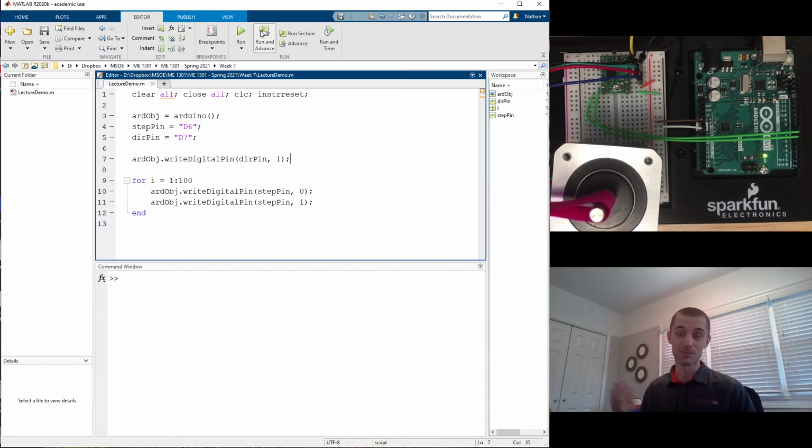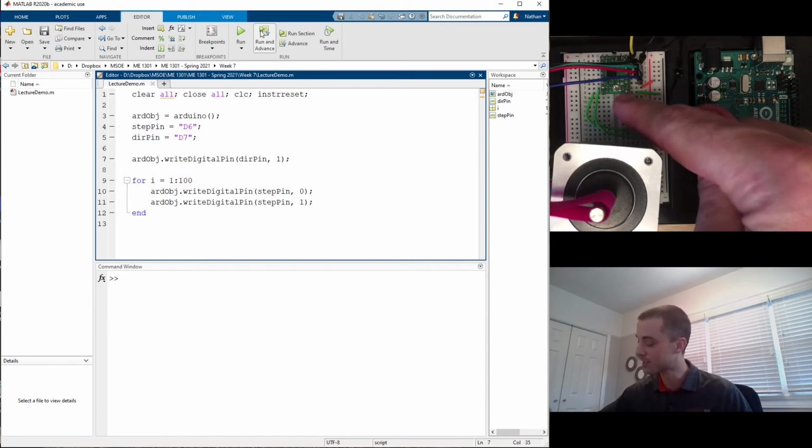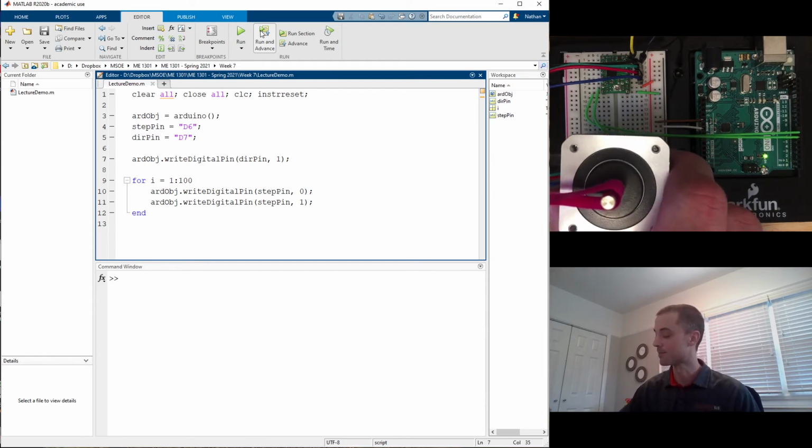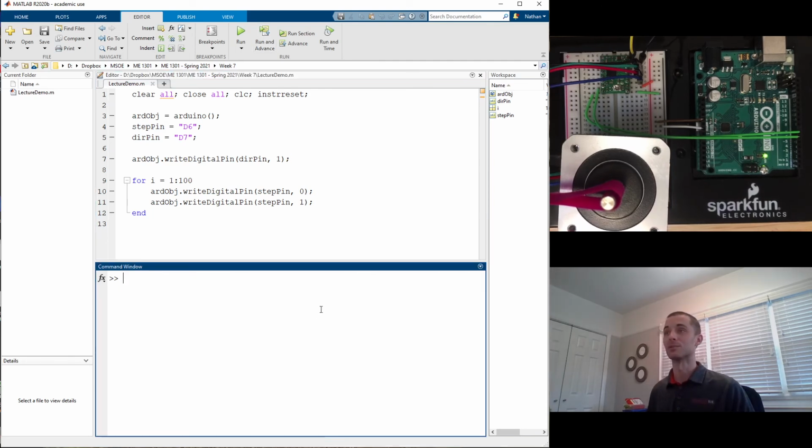If you do get some, which are incredibly cheap pretty much anywhere you order them from, one, make sure that your power supply is secured. But two, make sure you turn that little potentiometer so that you don't have too much current going through, because these chips, if you turn them up high enough, you can actually burn them out. It's not impossible to do, and I have a pile of partially burned out ones from previous student projects.